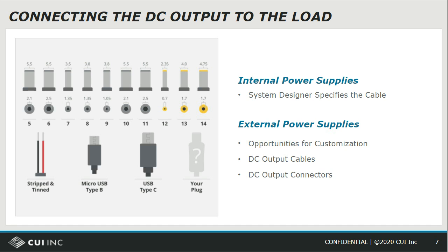And the latching may be what's referred to as bayonet, which is like 1/8 or 1/4 of a turn once it's inserted, or it can be a threaded one that takes numerous turns in order to secure the plug into the jack. Another type of latching is magnetic latching, and we've seen that on products recently. And then similarly, one might wish to have waterproof jacks. So all these sorts of variants are possible when selecting the DC output connector on an external supply.